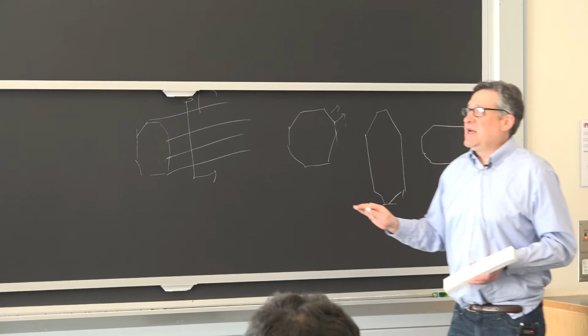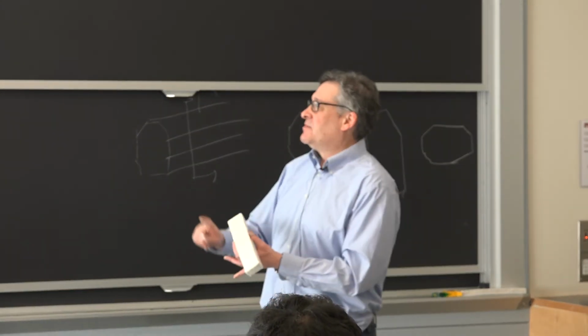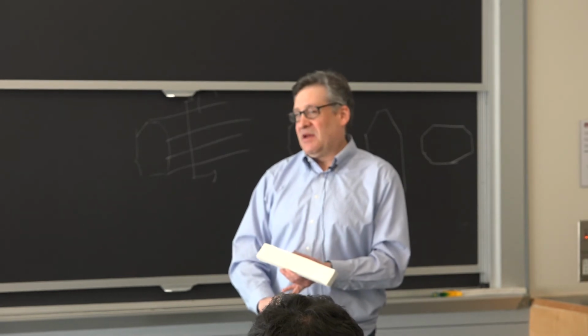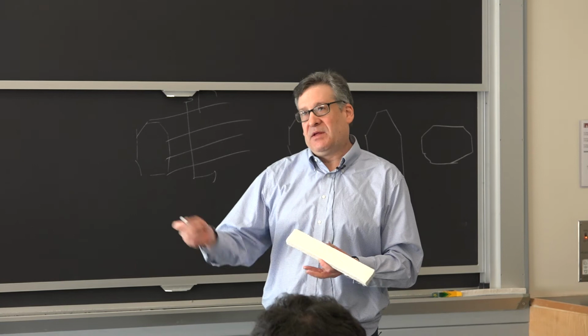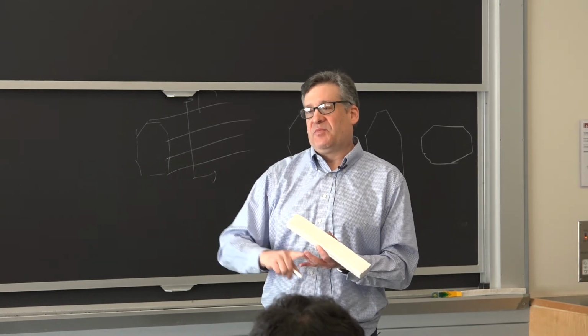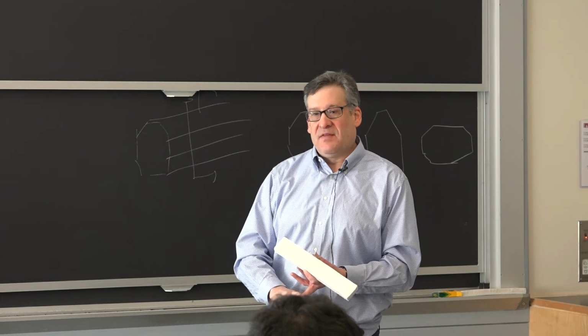But you can kind of see how this so nicely fits together. Like I said, topology optimization gives you the optimal load paths. Topometry optimization gives you the thickness of the panels, and then shape optimization gives you the right cross section. Probably I flipped the last two. Probably you want to do topology optimization first, shape optimization, then topometry optimization, and that gives you the most efficient structure.